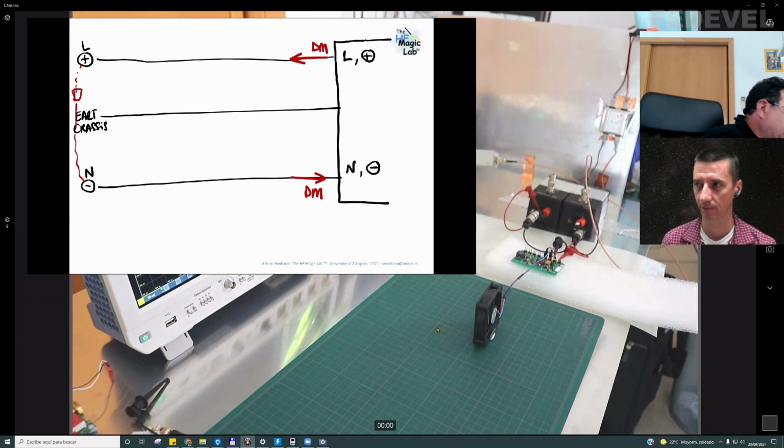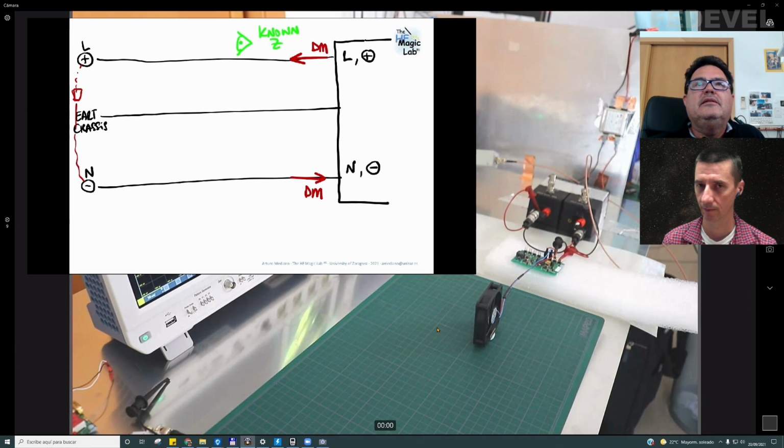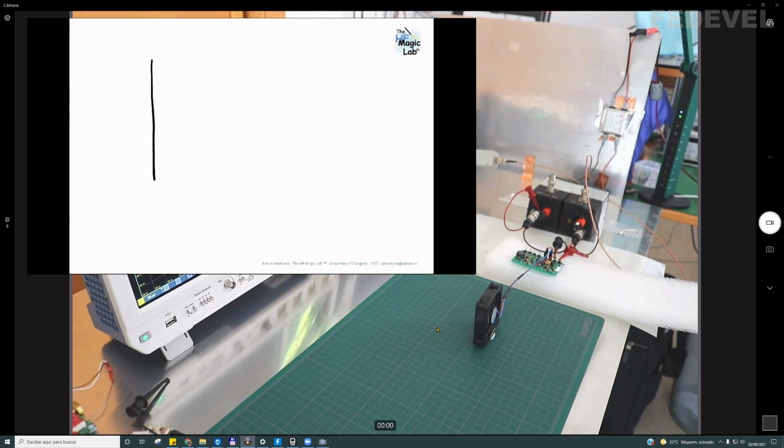So we need some kind of circuit to show to your product a known impedance, so we can compare the result of the measurement with the limits of regulations in any country, in any laboratory, in any condition. Okay, so the idea is, how is the impedance we see in a network? If you measure how much is the impedance in a typical power supply system as a function of frequency, you will find that it's something like this.